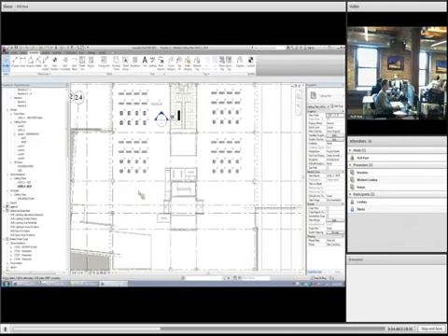So is it a group within a group? Nested groups. Yeah, exactly. It depends how you array. There are two ways. You can array with the group and associate, which basically creates nested groups, or you can array without grouping and associating. I kind of like them free, and then you group it together all at the end. I think that's easy. I don't know. There's not a perfect way.